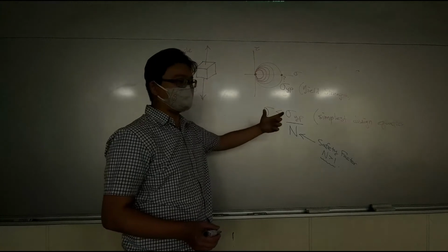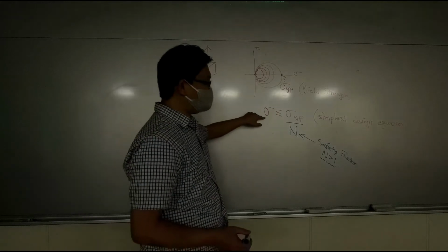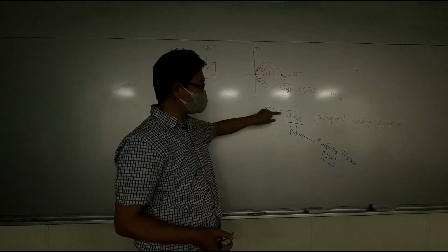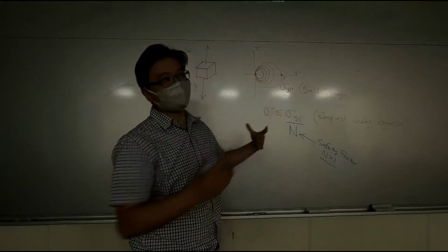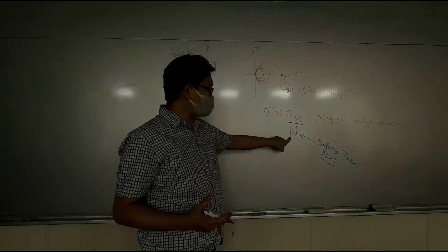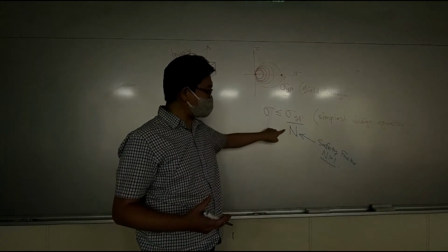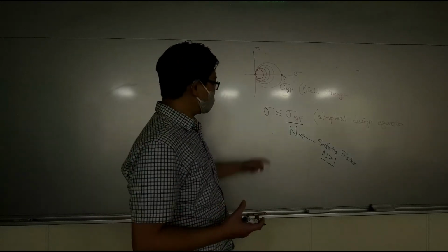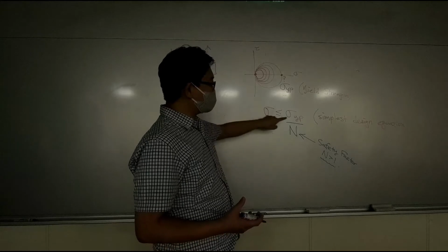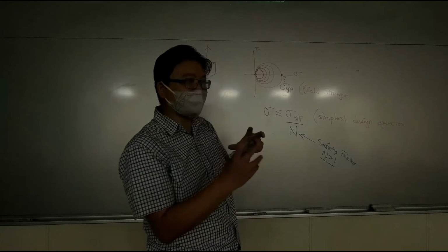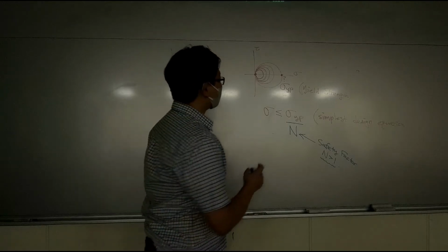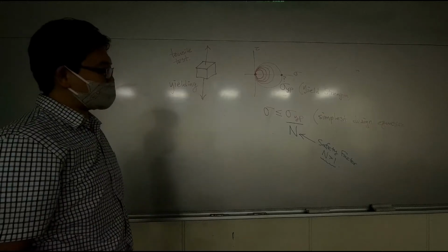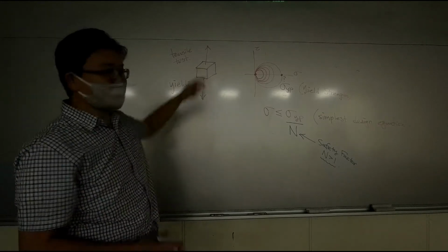But if your material has uncertainty, or if your load has uncertainty, and unfortunately, the true load is larger than the yielding point, then your material begins to yield. But if you apply a safety factor right here, which is having a value larger than 1, then your design is having a safer gap. So it's like we are treating the tensile test as a design that we're working on.